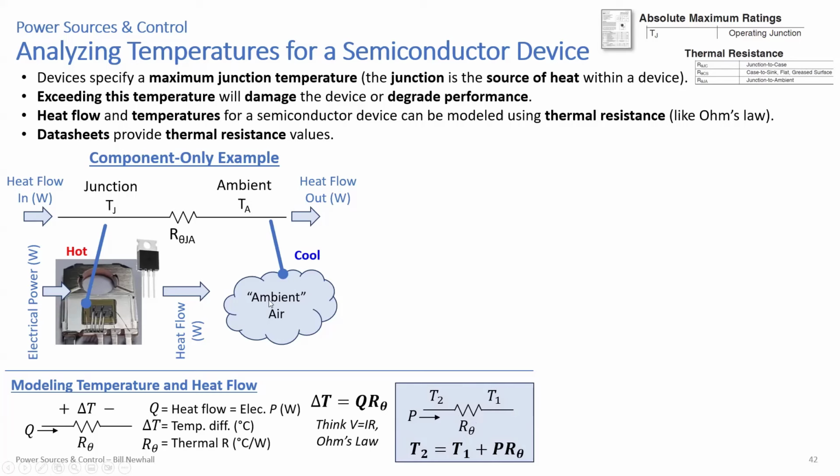If you had a device and you have air and you want to figure out the device's junction temperature, you usually know the ambient air temperature. You can look up the thermal resistance in the data sheet. And so you have air temperature, you have heat flow, you know what electrical power is going into the device, and you have the specified thermal resistance, so you can get a swag of T2, before you go and do some more detailed thermal analysis with modeling tools.